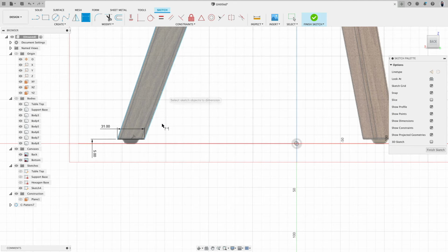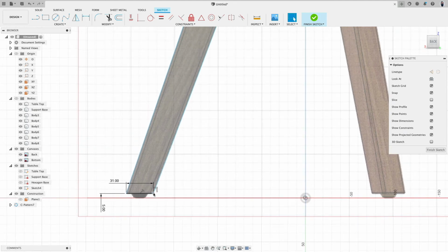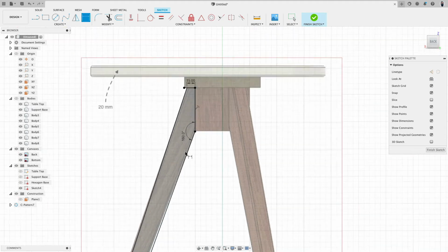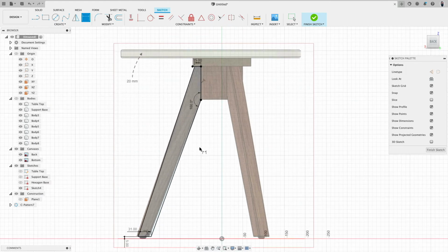These two lines are blue. That means if I press escape, I can move this still. So various ways to specify this. Specify meaning to prevent them moving. I can add a radius. Well, maybe this should be 160 degrees. Or 159.